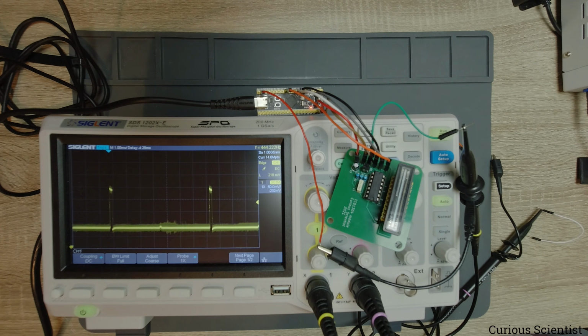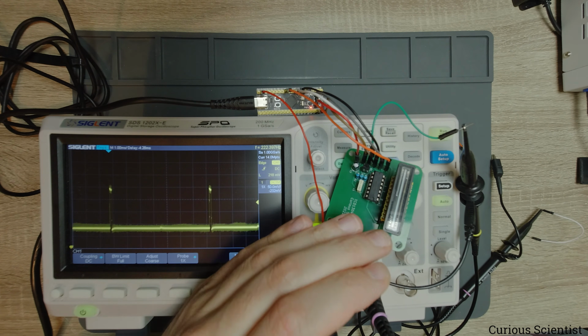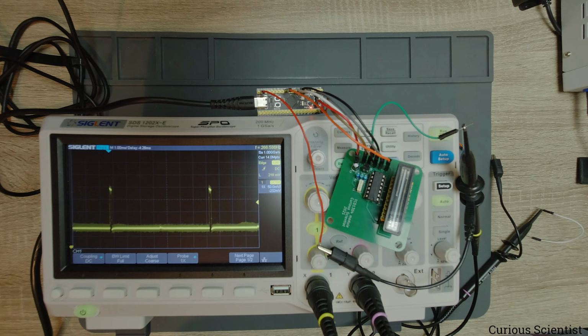because as you can see, or as you will see, it is relatively fast to set up the microcontroller in order to control this CCD. But in order to be able to do that, we have to deeply understand how this microcontroller works and how the CCD works. So how the different gates are clocked and how they work, how we read the pixels, and how we, for example, apply a certain integration time, and so on and so on.